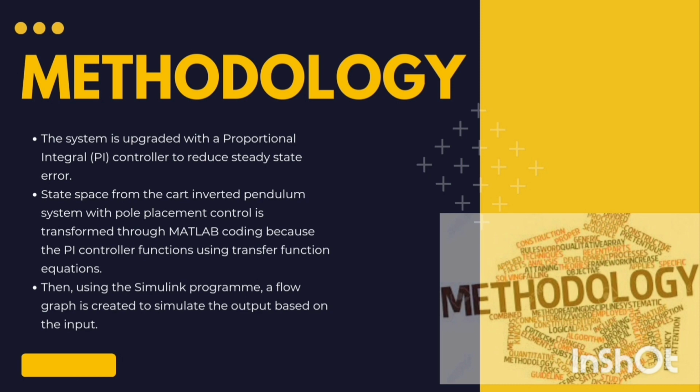I would like to spare some of my time to present about the methodology first. The system is upgraded with a proportional integral (PI) controller to reduce steady state error. The state space of the cart inverted pendulum system with pole placement control is transformed through MATLAB coding because the PI controller function uses a transfer function equation.